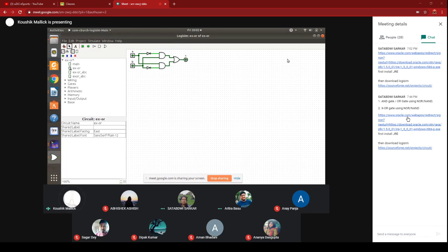Now this can be directly used in the new circuit. Look here, I have drawn this circuit from the previously saved item, and if you put your mouse over the input and output spaces, you will see the name of the variable. Here A is given, B is given, and at the output X is given.